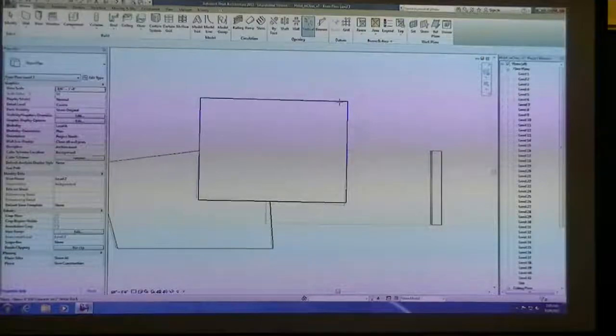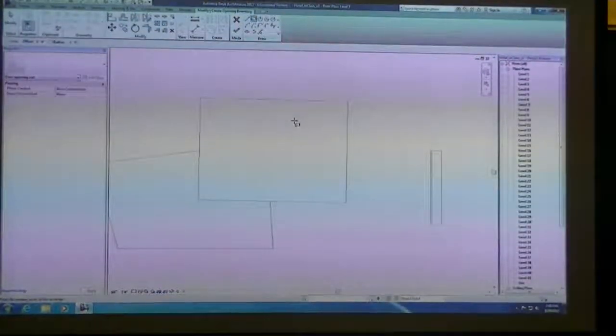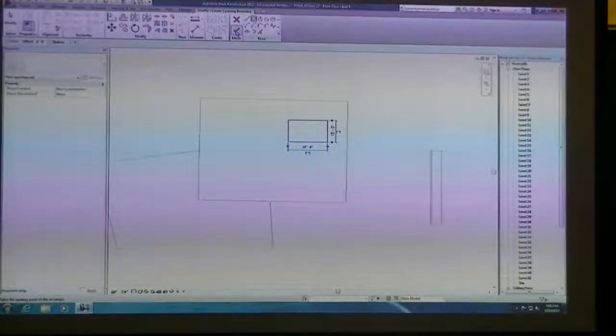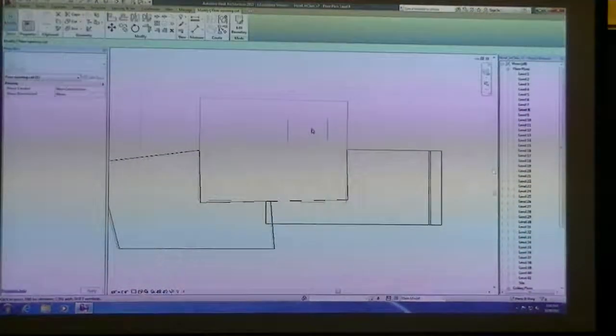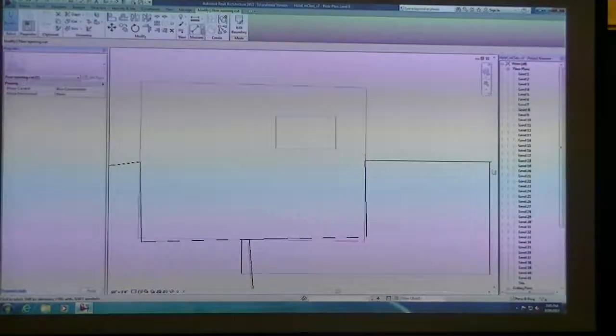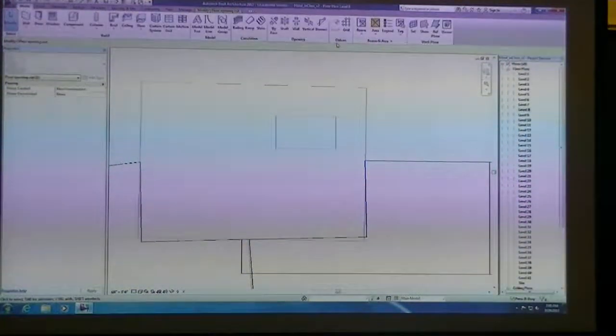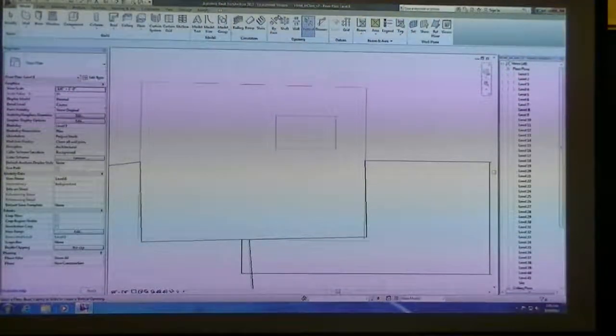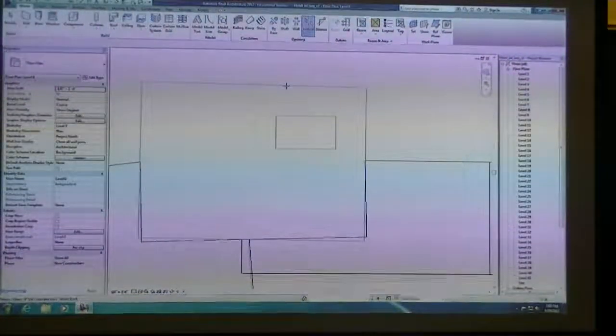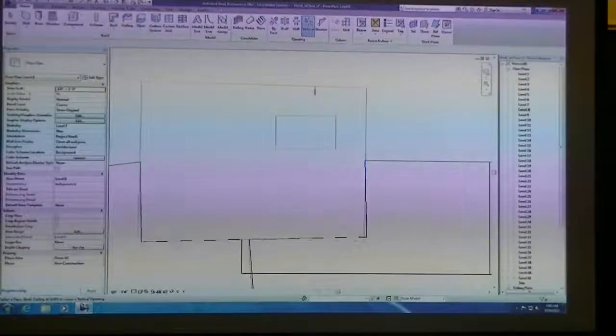If I create this vertical opening, it wants me to select the floor plate that I'm on, and then if I go up to level 8, I can see this other floor plate below where I made that opening. I'll click on vertical again, and let's say I pick the next floor slab up.